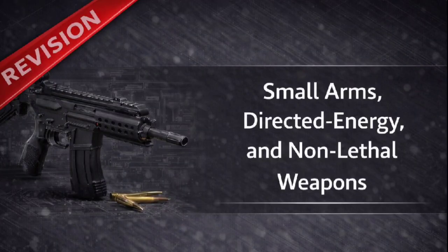We also see specialized protection for fixed positions, like anti-terrorist bulletproof glass. What are the two types, and what enables that famous one-way property? The two types relate to splinter management. You have low spall, or LS, which uses glass on both sides to minimize splintering inside the protected space. Then you have no spall, or NS, which uses glass on the threat side and a thick layer of polycarbonate on the protected side. And that stops all splinters. It ensures absolutely no splintering enters the crew space.